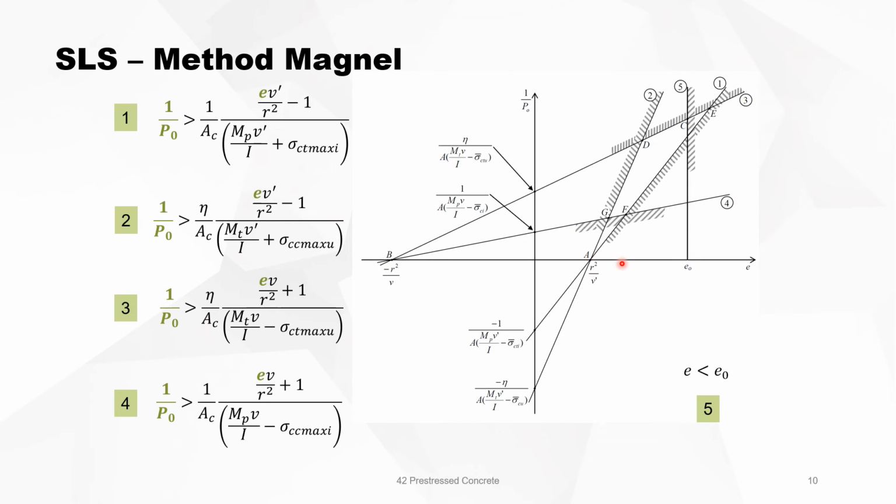and every point inside this figure is a point that complies with sigma T max and sigma compression minimum and maximum. So with the chosen values of the stresses, you can now calculate the needed eccentricity and the needed pre-stressing force. You can see easily on this drawing that there is no one solution. There are different solutions. You can use big pre-stressing force and a small eccentricity, or you can use a small pre-stressing force and a big eccentricity. We prefer to work in this region.